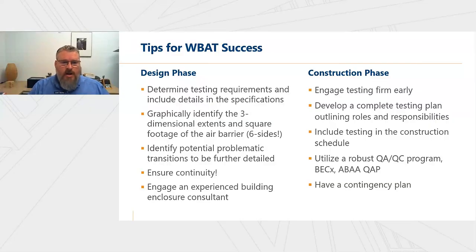So anything we can do to address it, it's usually those transitions between systems that tend to be the most vulnerable to air and water leakage. It's a good idea, especially on large commercial work, to engage an experienced building enclosure consultant that may or may not also do the testing. It's good to bring on whoever's going to do the testing